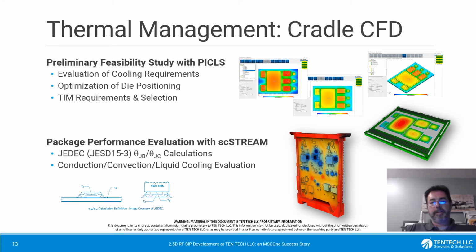We don't necessarily know right away in what kind of platform that's going to go. And that's probably one of the biggest issues, is those products are initially designed to be fairly universal. But when you start having 200, 300 watts to dissipate, this universality kind of goes out the window very quickly. You're left with only a few options, like liquid cooling or forced convection or heat pipes. You can't necessarily rely on simple free convection, natural convection to do the job.